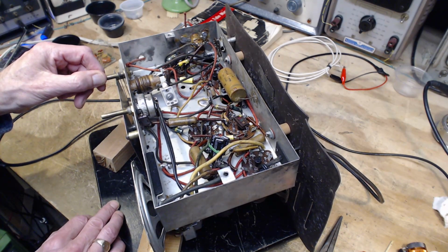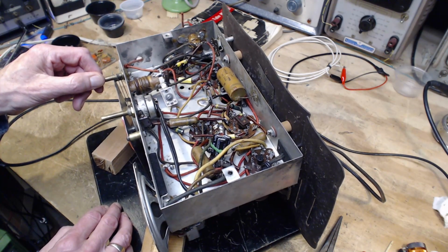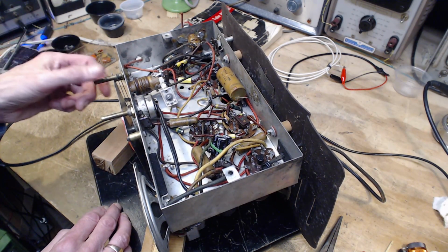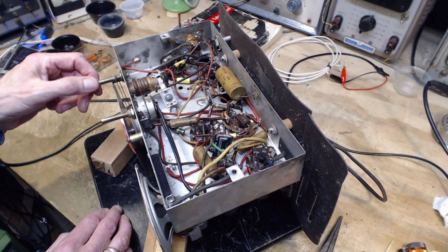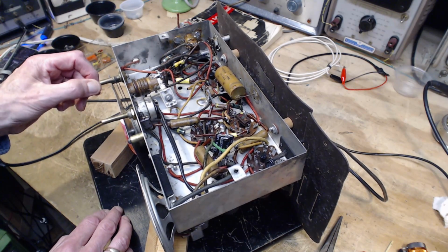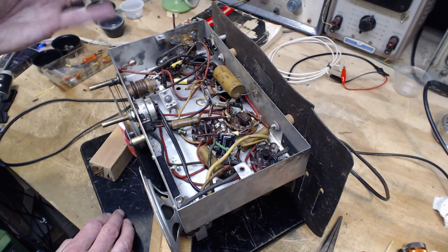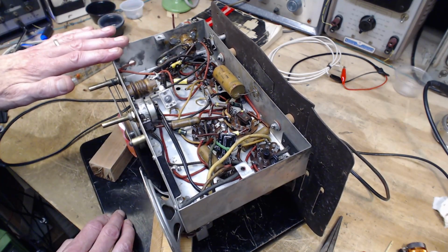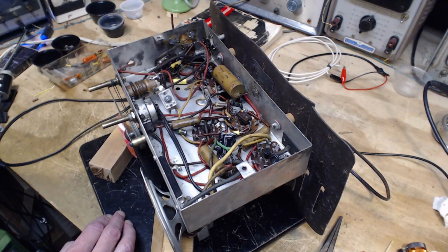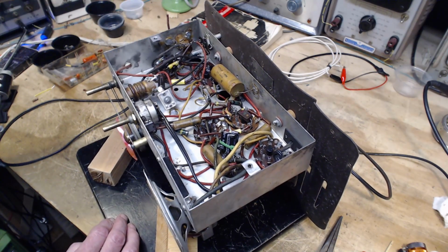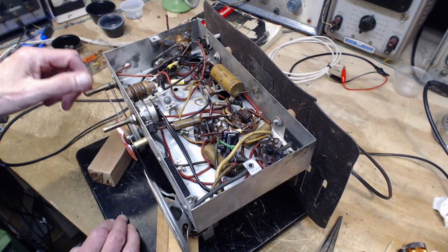It's an interesting sound there. That sounds like an open circuited grid. Oh. Also sounds like my hand is on the chassis. But it still has that open circuit grid sound to it. And that's kind of what's happened here. I've taken the capacitor off this high impedance circuit. There's nothing now holding it down, if I can put it that way.